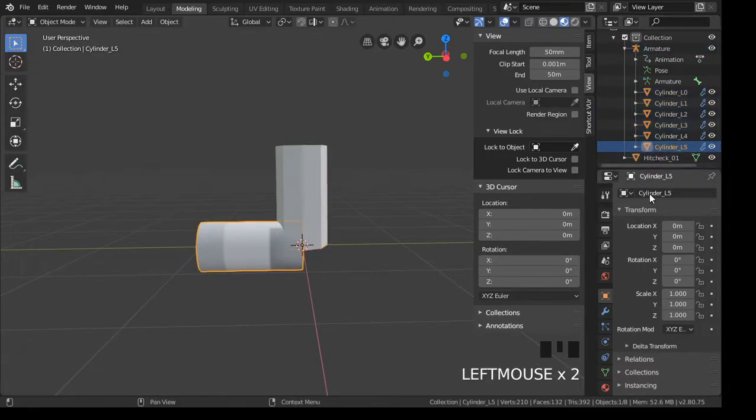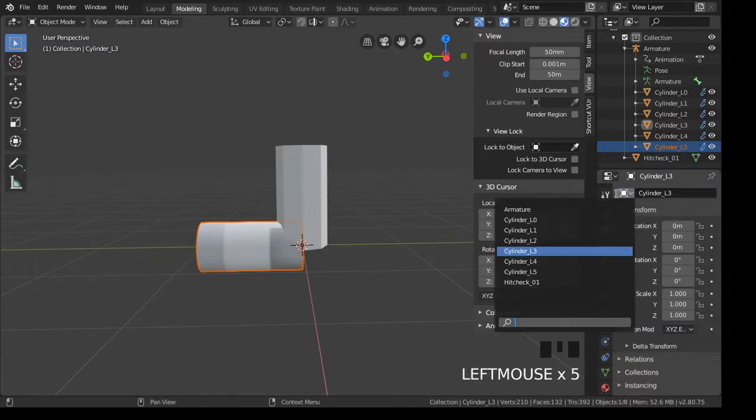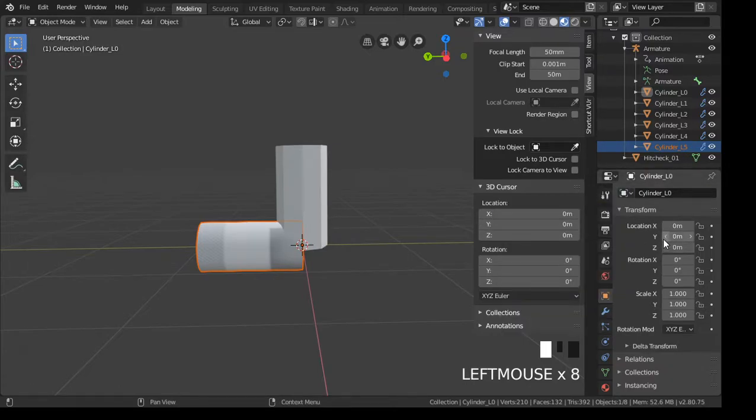And then all of your, you can do scene selection or use the drop down. Make sure the meshes themselves are zeroed out with a 1 scale for every single one of them, with the origin snapped where it's supposed to be. And they are. And then the armature needs a rotation on the x-axis at -90, and everything else zeroed out. And once all your objects are selected and you export correctly, then this animation will work inside of TMTK.